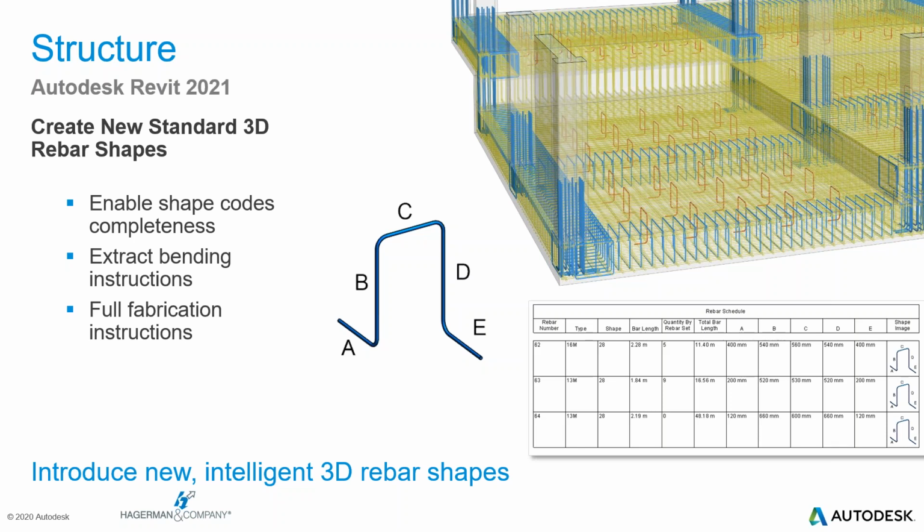Rebar couplers are used in reinforced concrete structures to replace normal rebar lap joints. In Revit 2021, you can now use rebar couplers to connect tangent arc-shaped bars in circular concrete structures, such as curved walls, concrete tanks, tunnels, etc. This new feature helps structural engineers and detailers create highly detailed reinforcement models and documentation.